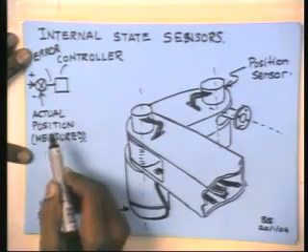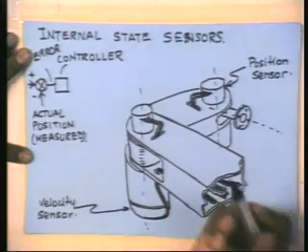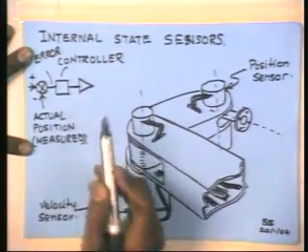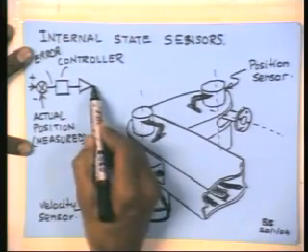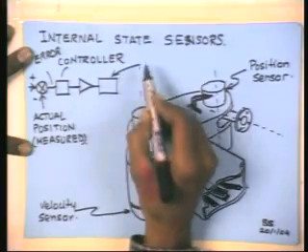It can take other signals too. In fact, it can look at the desired position and the next desired position to do something more intelligent. But at a very elementary level, the controller will look at the desired position, look at the actual position, look at the error, and then if the error is large enough, it's going to take some action, which is depicted as an amplifier. So the error is amplified so that it can actually drive some kind of motor or basically the robot system. So this is representing the dynamics